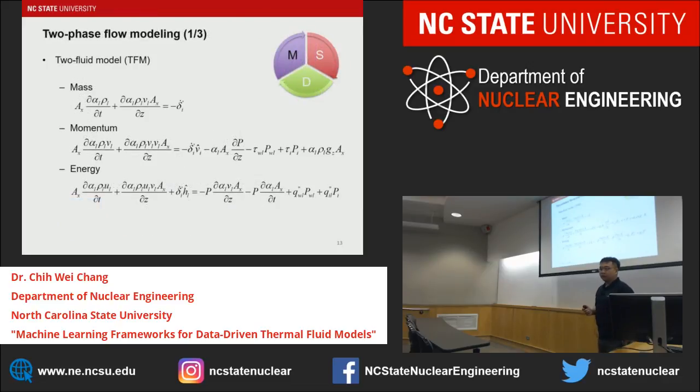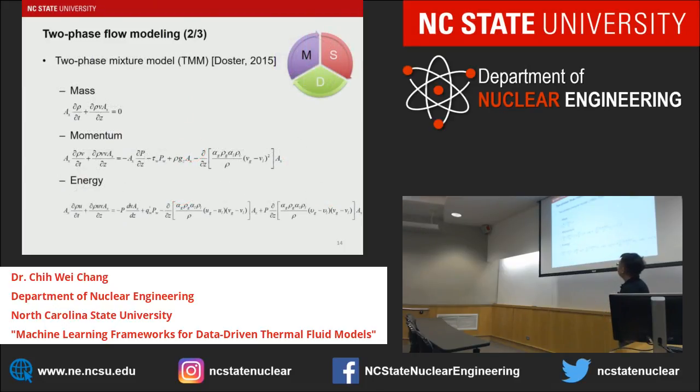For the two-phase flow simulation, we have mass, momentum and energy conservation equations. And we need a lot of different closure relations, like interfacial information, and we also need drag force information, which I circled in this slide. The two-phase modeling can also use a mixture model, which reduces the mass, momentum and energy equations into 3 equations, and also greatly reduces the number of closure relations.